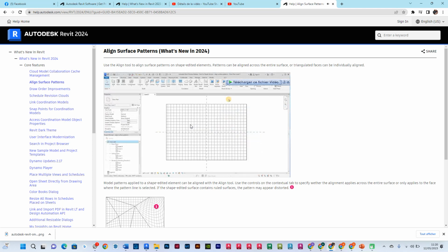When working with slab elements, you may have a surface pattern to represent a material or condition. In this example, we have a slab with a surface pattern representing tile. You can use the Align tool to shift the pattern if needed. You might want the tile pattern to be aligned to the center to equalize cut tiles on either side. On the Modify tab, click Align, then click the reference point, and then click Align in the pattern to align.